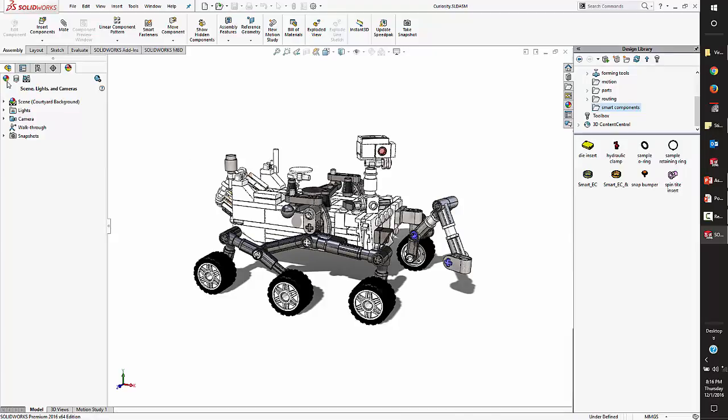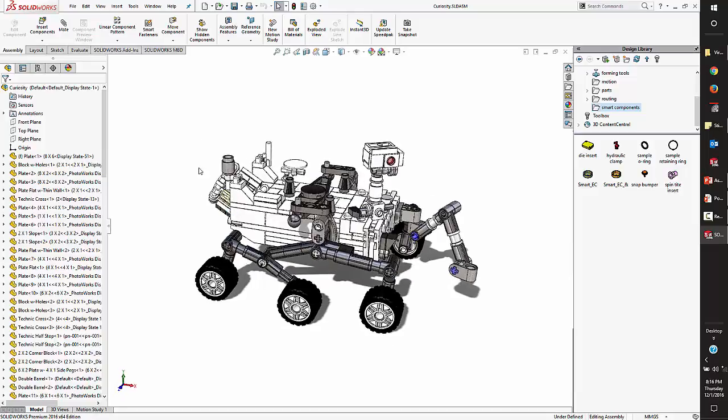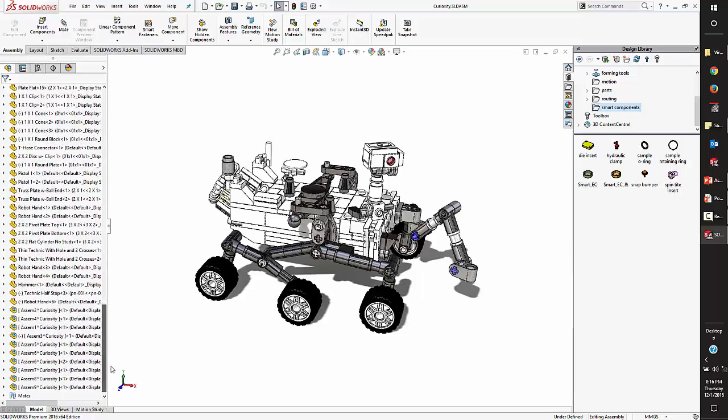So if you come in here, let's go SolidWorks. It's pretty exciting, isn't it? No, it's stupid. There we go. So if I look through here, I've got all my components sitting there, all nice and pretty. Now, if I go down a little bit farther and look at my subassemblies, you'll see that there is a square bracket around them, and they do have a little caret symbol with the name of the assembly in there. That's a virtual subassembly. In fact, do you see all those subassemblies right there? They don't exist as a particular file on my hard drive at this particular time. They're actually stored inside of this assembly itself.